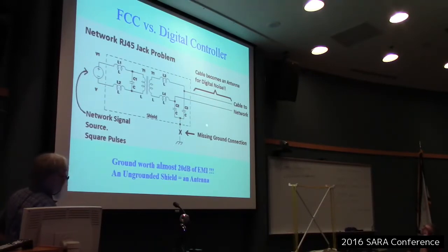And when somebody's failing by like 8 or 10 dB and putting a shield in one place brings you down 20, you say, okay, you've got something that ought to pass. And when it was run to the test lab, it did pass. Another problem this particular box had was backlighting for a display, with the fluorescent tubes driven by RF. And the cabling for those got mixed with the power in cable, so we had a cable layout fix for the same box. But it was interesting. That was the greatest part of the problem, and a little spring clip was fabricated to ground that case. Problem solved. It passed at the test lab with good margin next time.